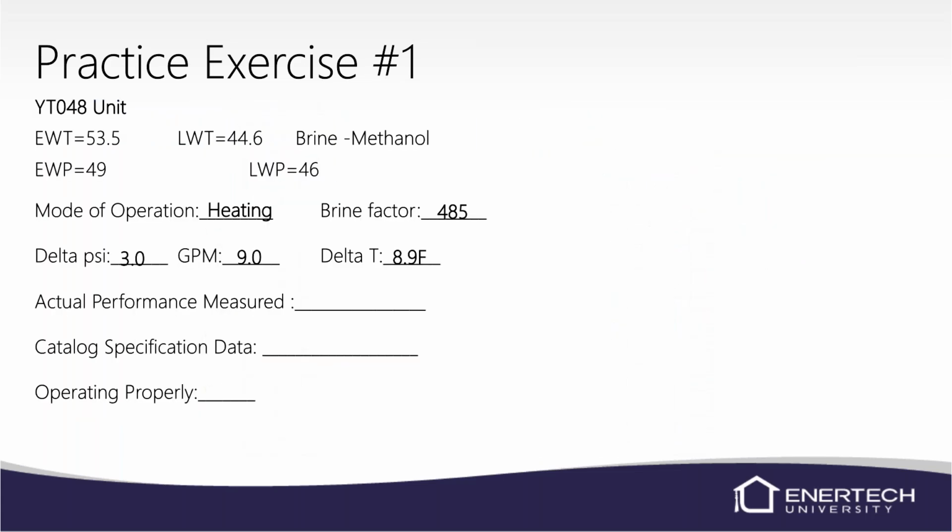So we were at 38.8. At 39.6, 10% below that would be somewhere around 36,000 BTUs, 35,000, somewhere like that. So we're within that 10%. So yes, the unit is operating properly. There's no need to put your refrigerant gauges on there, none of that. No superheat, subcooling. The unit's doing all that it can.